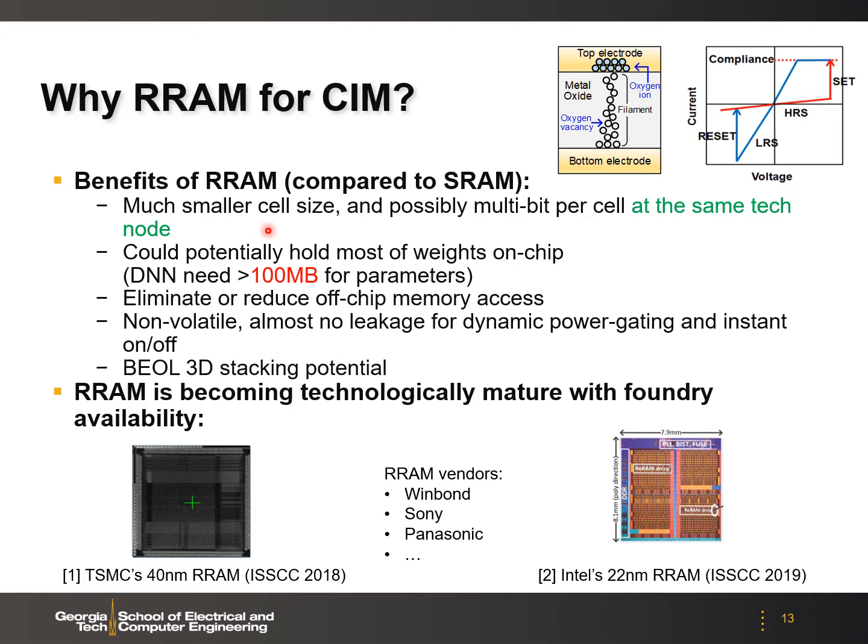And also, RRAM is a non-volatile memory, which means we can power off the chip in the standby mode. So there is almost no leakage with dynamic power gating, and it can enable instant on and off operations, which are very useful for inference at the edge. And RRAM is back-end-of-line compatible, so we can potentially stack the RRAM on top of each other for 3D integration. RRAM technology today is becoming technologically mature with foundry availability.